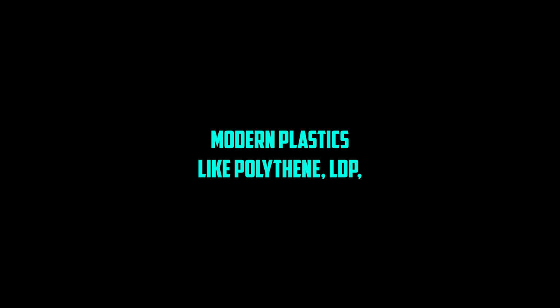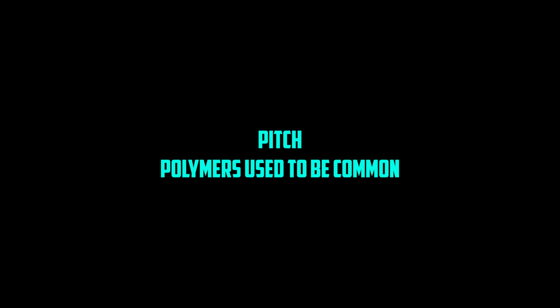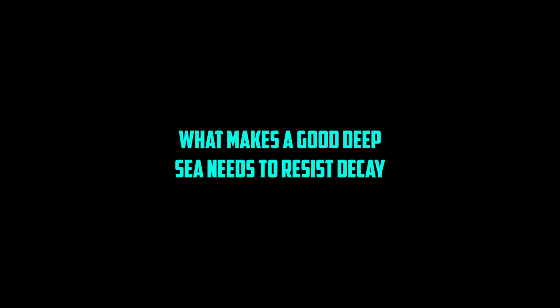Keeping water out, damp-proof courses, DPCs. Critical stuff. Absolutely vital barrier against rising damp from the ground. Lots of materials mentioned: bitumen, felt types, modern plastics like polythene, LDPE, polymer-modified bitumens. Pitch polymers used to be common but had health concerns. What makes a good DPC?